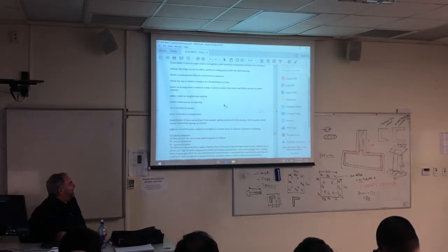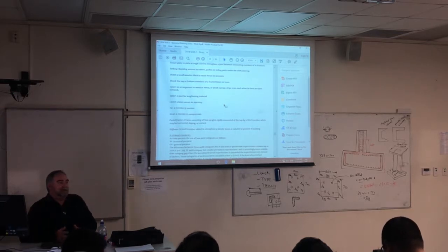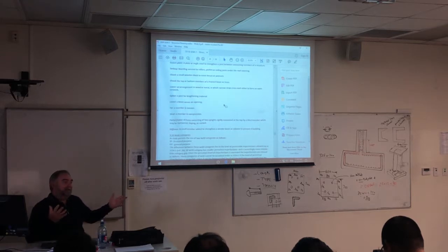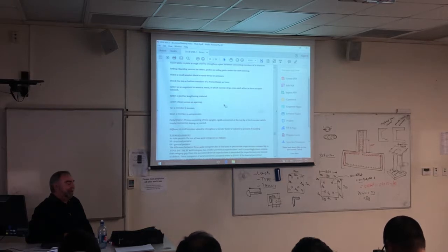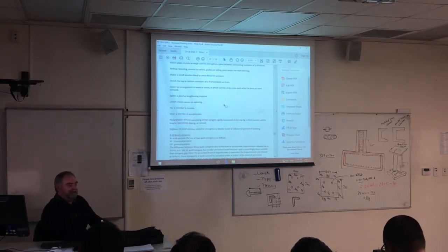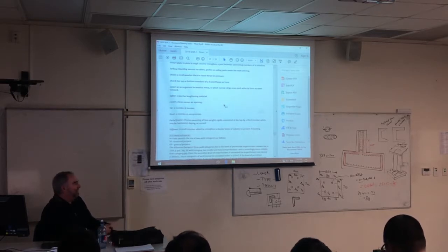The most important thing I found with steel work was they wanted you to determine the height to boundary as soon as possible before they put the steel members in place. Because if they did it once, they bolted them all together, it's too late. Okay? Next thing you know, you've got a legal fight on your hands with neighbours, etc. So the little amount of surveying that I did on construction sites, it was pressure work. We had to get there, get it done and get an answer to them before sort of 5 o'clock that night.